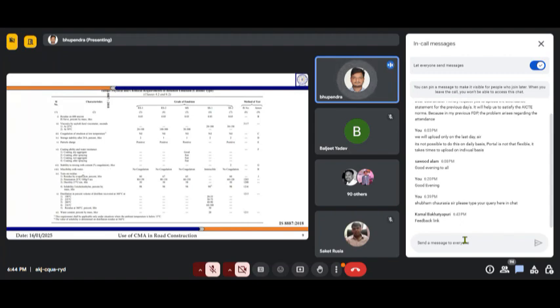miscibility with water. Then we take out the residue also. In emulsion there is water, and then there is bitumen present. If we take the bitumen out of the emulsion, that is called the residue. On the residue, we check the evaporation. After heating up, how much residue is left, meaning how much bitumen is present in your emulsion. That is checked. Then the penetration value of that residue we check. Then the ductility value of that residue we check, and the solubility also, meaning how pure that bitumen is.